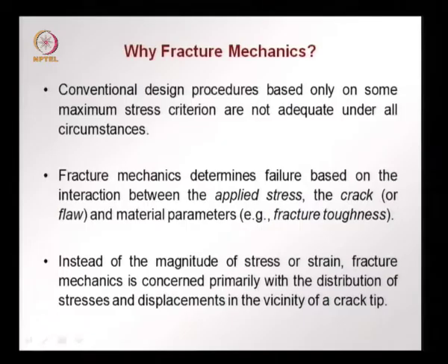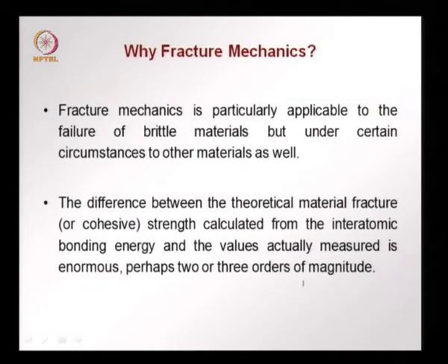Instead of the magnitude of stress or strain, which are very difficult to determine and have very high values in any case near the crack tip, fracture mechanics is concerned primarily with the distribution of stresses, the stress fields and the displacement fields in the vicinity of the crack tip. This is particularly applicable to brittle materials like concrete, rock, glass, ceramics and so on, but under certain circumstances other materials also fail in a brittle manner, like we saw in some of the examples of the pipes and the girders.